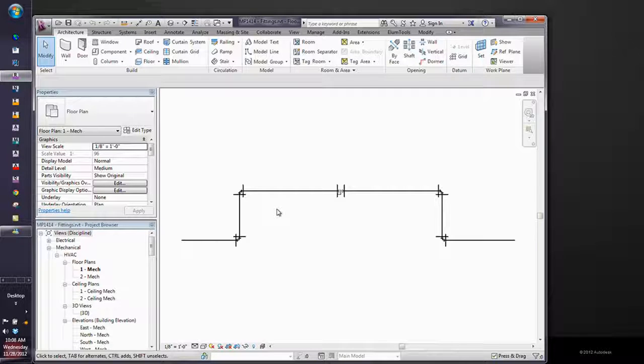And so what Autodesk did is they put a couple of extra components in all your fittings. They have model lines to actually show the tick marks, and they have some other graphics that are turned on and off using display configurations in here. So when you're in coarse and medium view, these model lines show up. But if you don't want them to be there, or if they're not right, they really make the drawings look bad. And if they're not defined correctly, they can really make it look bad in this case.